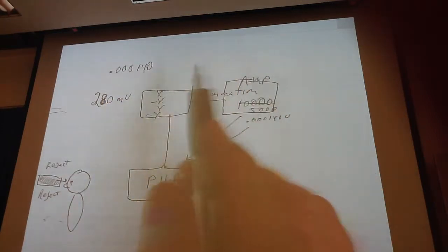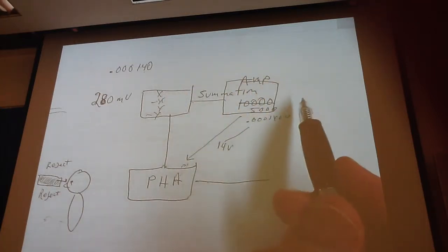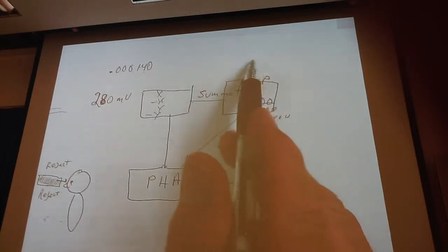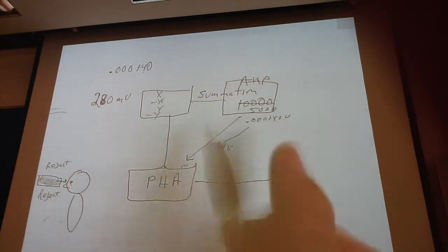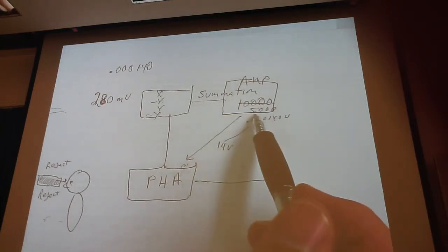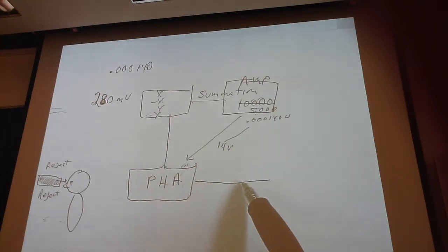Okay, if I had 70 millivolts coming in, what would I do? 20,000. I would increase the amplification to 20,000. So when you push a button, what you're doing is changing the amplification for each radionuclide that you want to look at, so that it will go through that 14 volt pulse height analyzer. Does that make sense now?